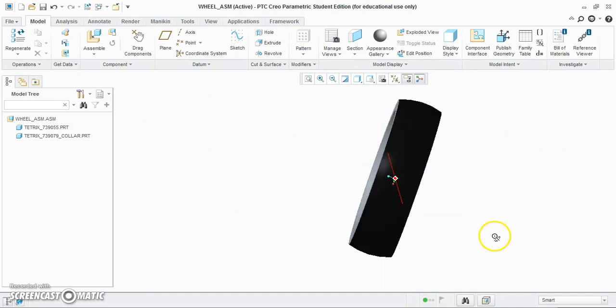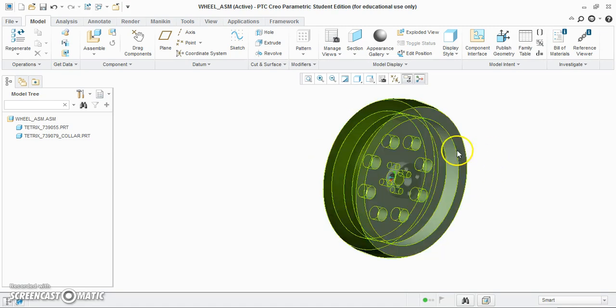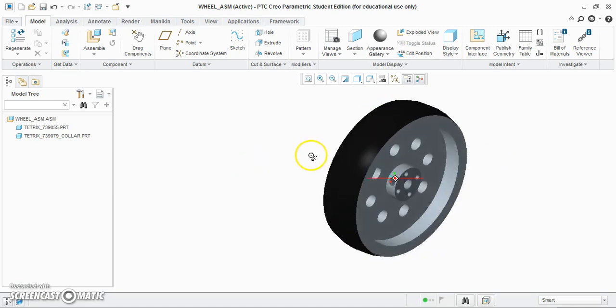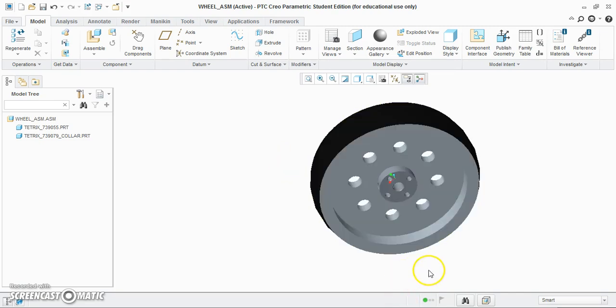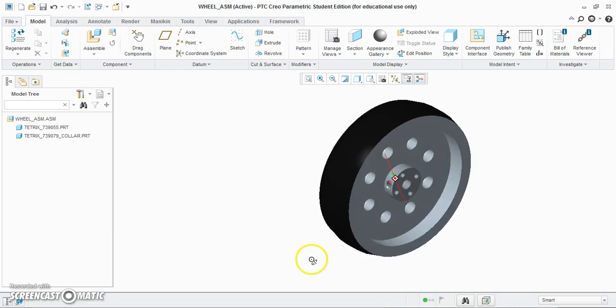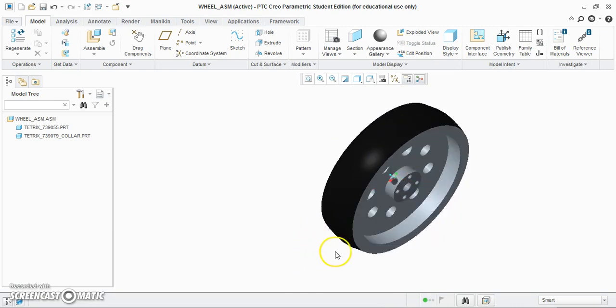So now we want a wheel. Now the thing about a wheel is, in your model, you want your wheel to be able to rotate. So a good thing to do is make a pin constraint so that it can rotate about the axle.